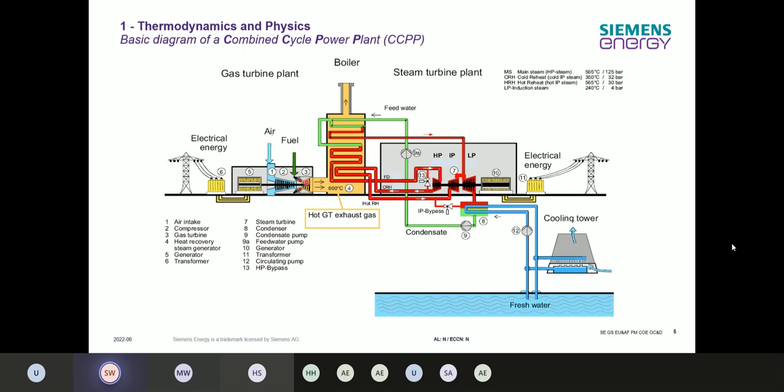We're doing work on the rotor, the temperature is dropping, and the energy is absorbed into rotation energy. With this rotation energy, we're driving our compressor and our generator and producing an electrical power output.